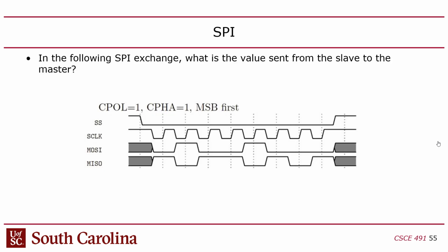Notice that in this case, this works out very well because these dotted lines just happen to intersect the rising edge of the clock. So if I want to interpret the data, I just have to figure out where MISO intersects each dotted line. That's pretty easy: 1, 0, 1, 1, 0, 1, 0, 1. Just look at the intersection point. Sometimes, depending on the timing, the dotted lines may not line up that way, but in this case, the dotted lines are the sample point.